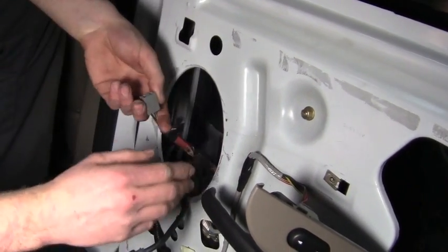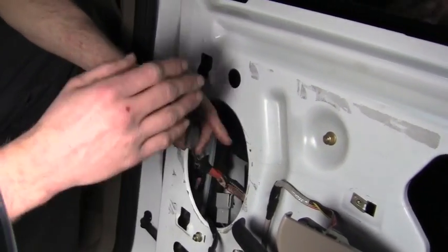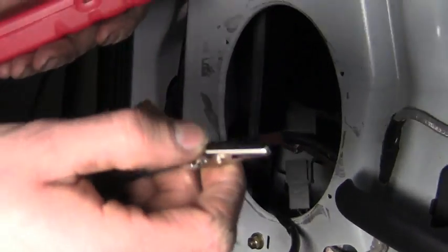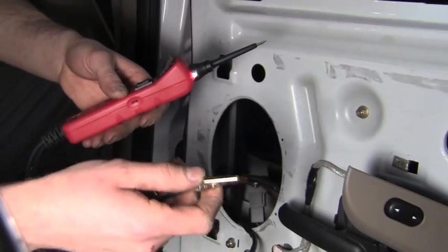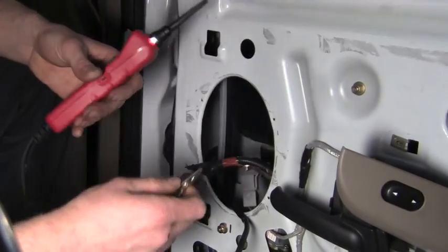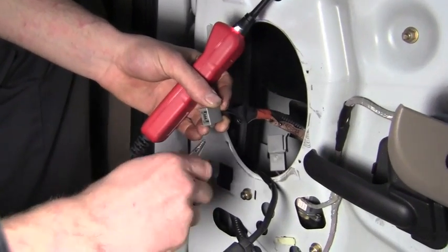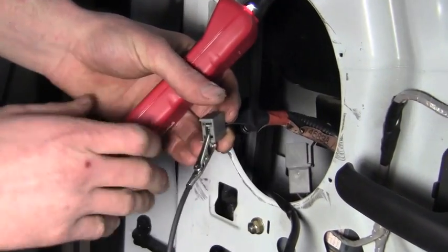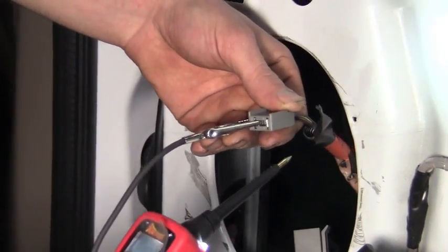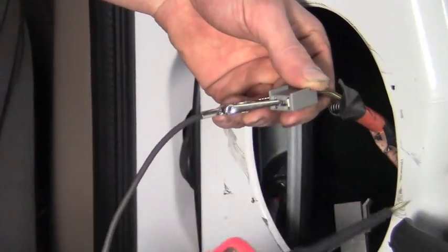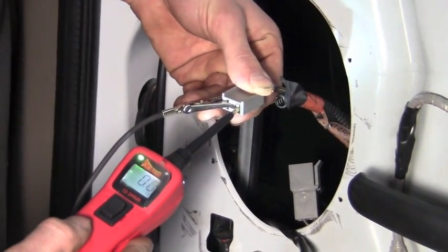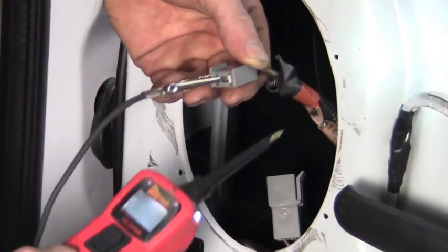Now, because we have the motor out of the circuit, it no longer has ground provided to it from the vehicle. Now our power probe has a ground strap on it that we can use to provide ground to the circuit. So we're going to go ahead and place that on one side. Number 1 here. It's wet on top. When I place the power probe on the other side, that should be a closed circuit. Now as that light comes on, that tells us that we have a good circuit and good ground.